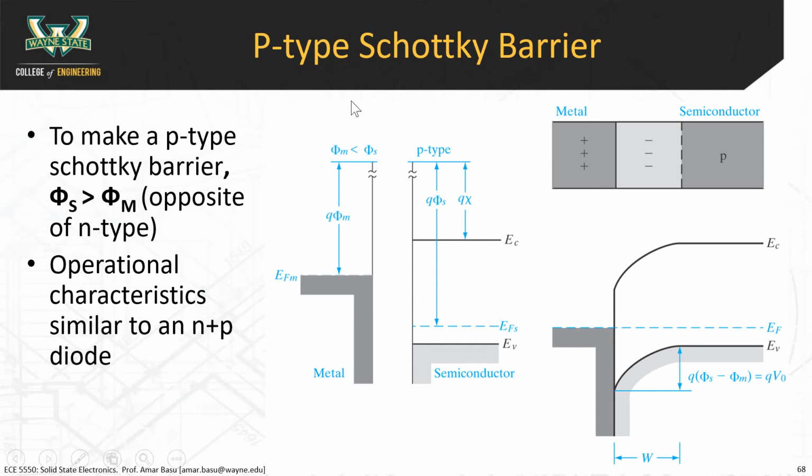So I'm not going to go through the whole steps of drawing the band diagram again. I'm just showing you a shorthand using a diagram that's in the book. So imagine initially when we bring the two materials together, the E0s are lined up. Okay, that's this blue line up here. So let me just label that E0. This is the vacuum level. Notice that the Fermi levels are not lined up with each other yet. Okay, so within a very, very short time, equilibrium is established.